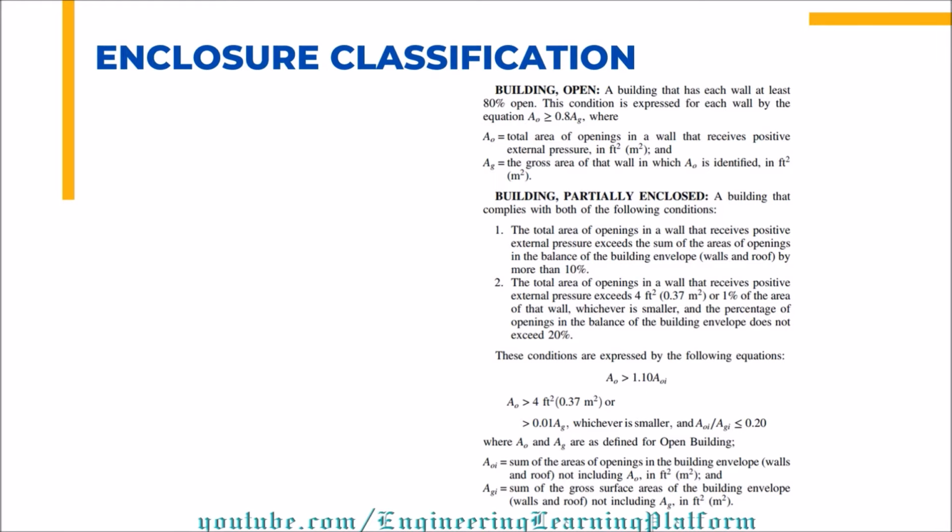Along with that, if we combine all the openings in other parts of the structure, the percentage of opening should not exceed 20% of the building envelope. So those are the two conditions that should be satisfied for a building to be partially enclosed.